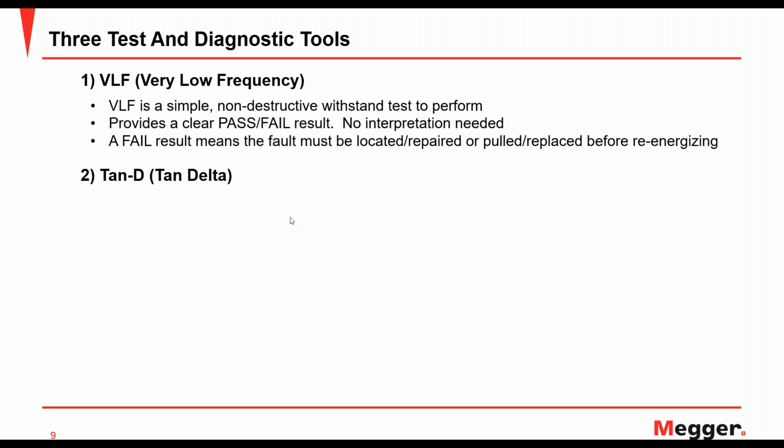The first is VLF, or very low frequency. VLF is a simple, non-destructive withstand test that can be performed, similar to a high pot, only performed at 0.1 hertz and non-destructive. The beauty of this test is it provides a very clear pass or fail result where there's no need for interpretation. What I mean is, if you perform a VLF test, you apply your VLF withstand for 30 or 60 minutes, and if you pass, you have no failure. So it's very clear.